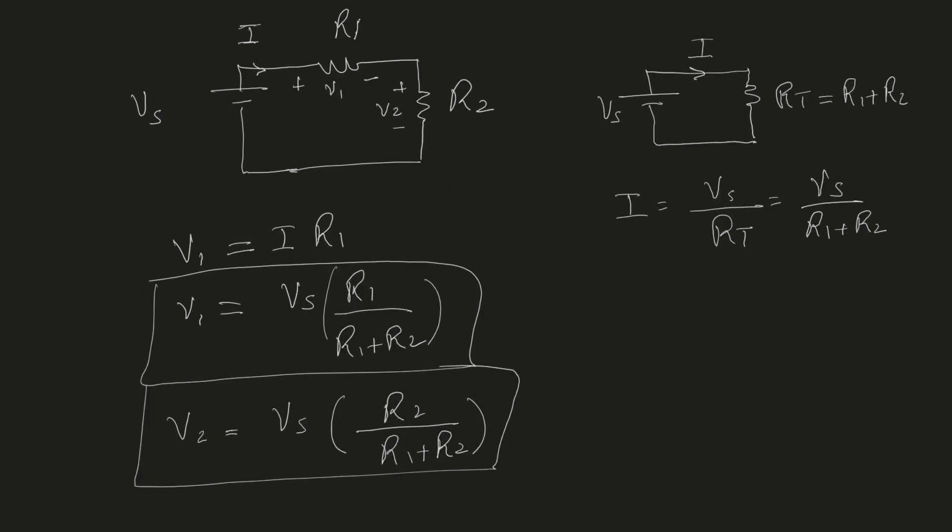Now VDR gives us a quick way to find the voltage across any resistor. If we remember how to use this VDR equation, then we actually do not need to calculate the amount of current. We can just use this equation directly, and it will save us some time. However, this equation was obtained using Ohm's law by first finding the value of the current. So therefore, VDR provides a convenient way to find the voltage, but there is no new method or information that is contained in VDR.